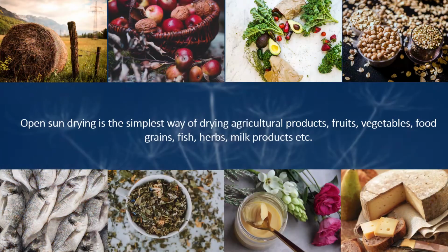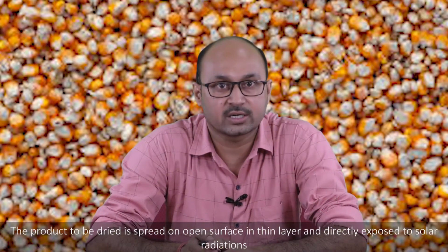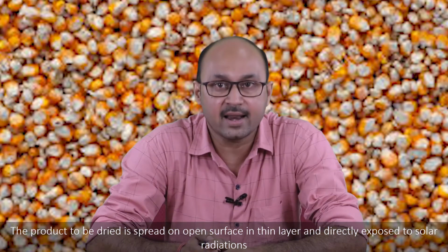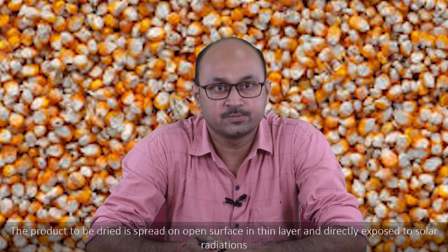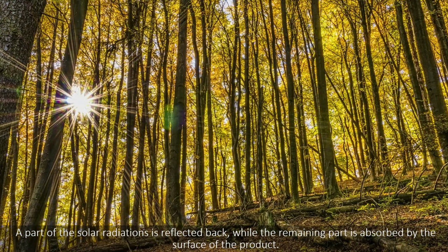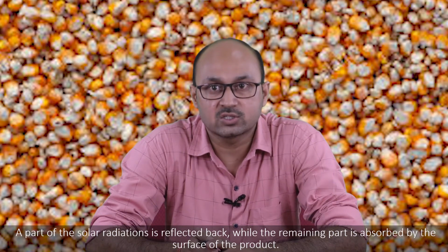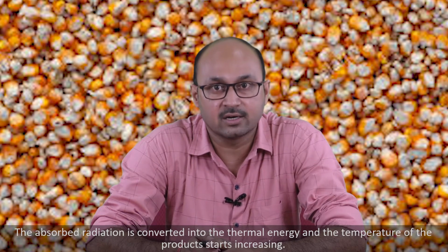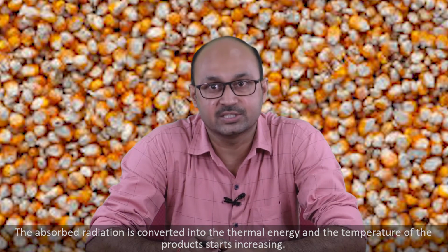Open sun drying is the simplest way of drying agriculture products, fruits, vegetables, food grains, fish, herbs, milk products, etc. The product to be dried is spread on an open surface in a thin layer and directly exposed to the solar radiation. A part of the solar radiation is reflected back while the remaining part is absorbed by the surface of the product. The absorbed radiation is converted into thermal energy and the temperature of the product starts increasing.